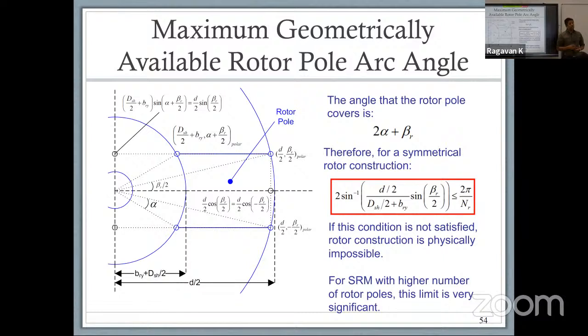So these are basically pre-design calculations that you do. They are often also referred to as pre-design qualifications, specifically to see if a given motor is suitable and fit for the job at hand. That's one of the reasons why you use options like MotorCAD and such. ANSYS has these front-end tools, but that's once again an iterative algorithm.